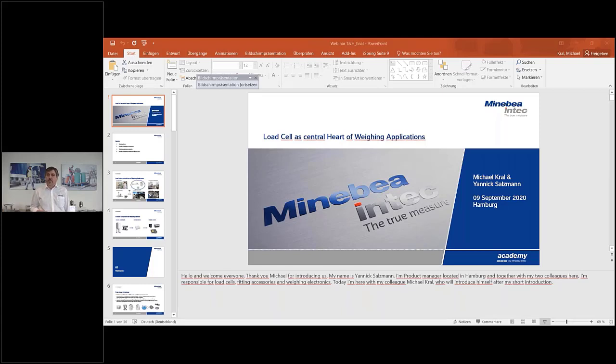The main difference between accuracy and repeatability: we have defined the accuracy already. Now the repeatability is the ability to determine always the same results of the measuring procedure if the measuring procedure is being repeated, independent of the accuracy of the results. Also, results with deviation can show a good repeatability if the indicated deviation is always the same. The high accuracy is essential for a constant quality of the production.